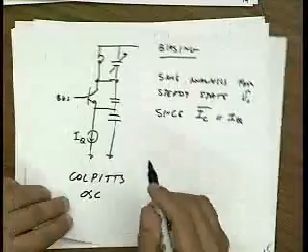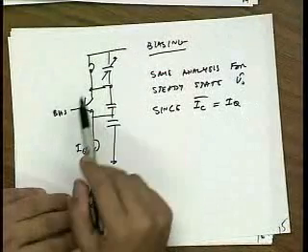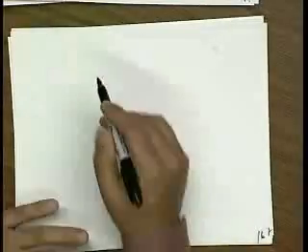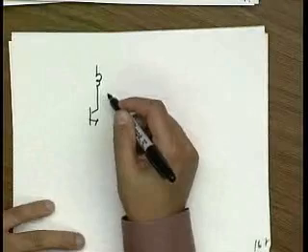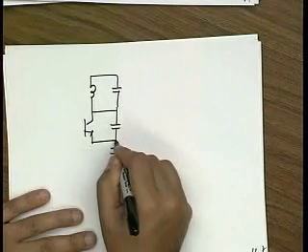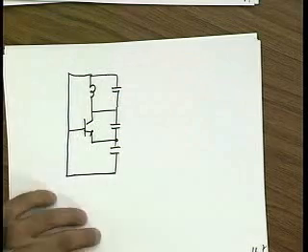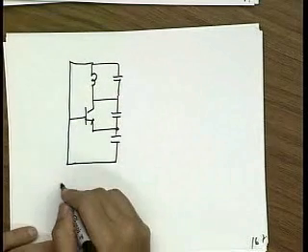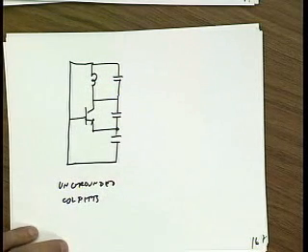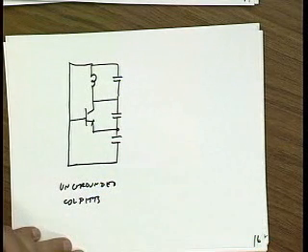So let's take this oscillator, and instead of grounding, so AC-wise this point's grounded, and this point's grounded. Let's just connect all those points together. So I have the following circuit. So remember, this point is grounded, and this point is grounded. So now, this is an ungrounded Colpitts. And if I ground the base, I get the Colpitts oscillator that I just saw.